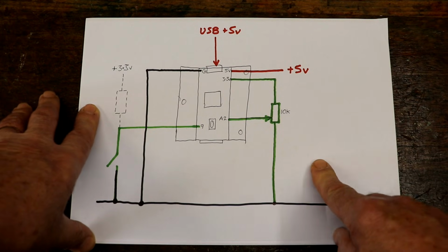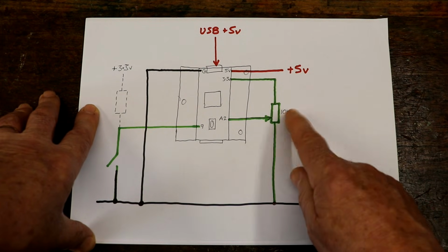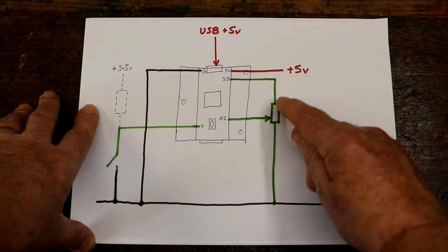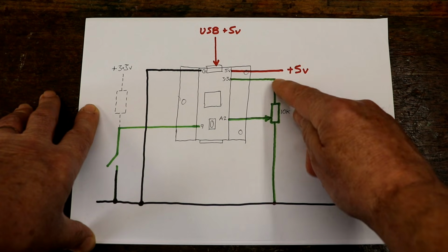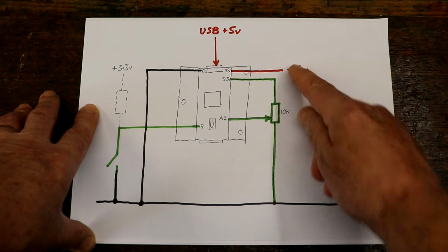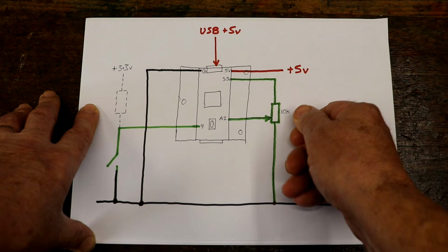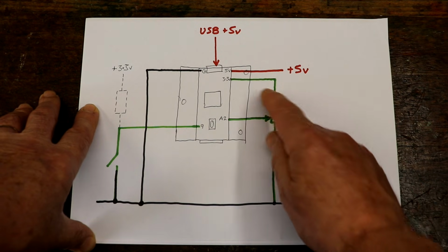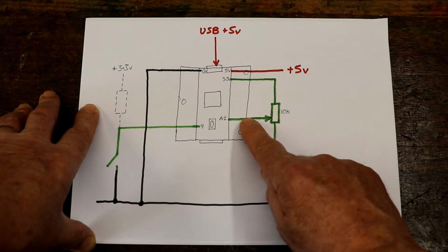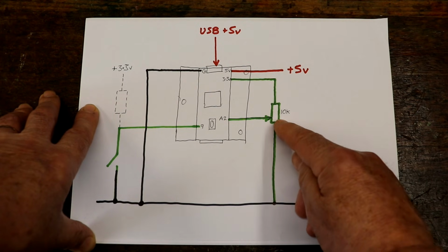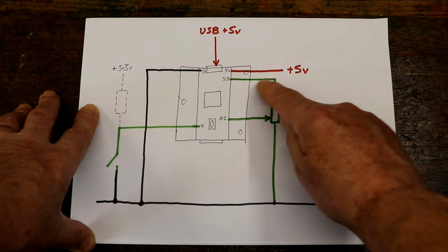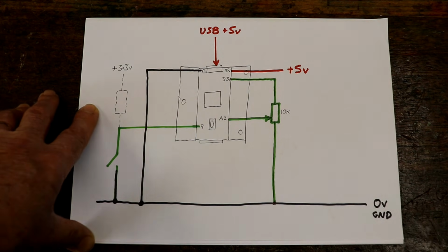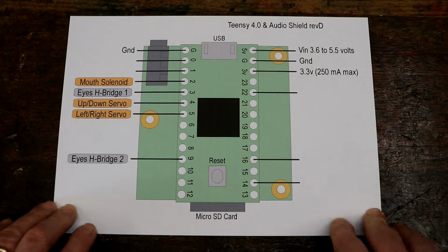If you want an analog input, say with a potentiometer, again that mustn't exceed 5 volts. It's very easy to make the mistake and connect one of the legs to plus 5 volts, but that would mean that as you turned the potentiometer, or the volume control so to speak, up, the analog input would go to 5 volts, and again that would damage it. So always make sure, if you want to have potentiometers, that they all connect to the 3.3 volt output on the Teensy.